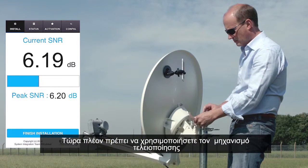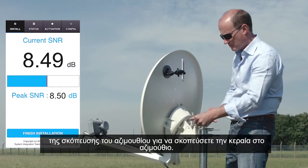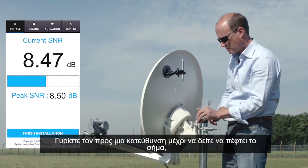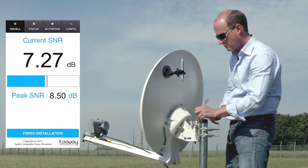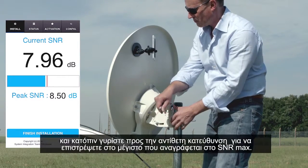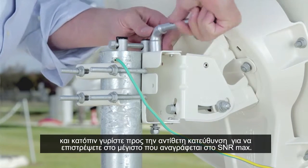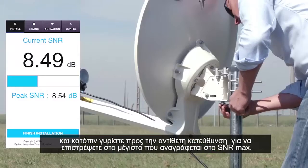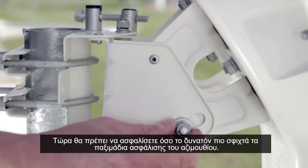Now you must use the azimuth fine pointing mechanism to point the antenna in azimuth. Turn it in one direction until you see the signal drop. And then reverse the direction to return to the maximum indicated on the SNR max. Now you must lock off the azimuth locking nuts as tight as possible.